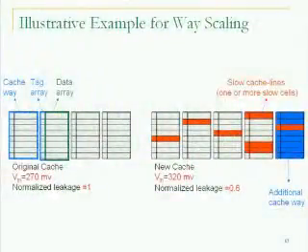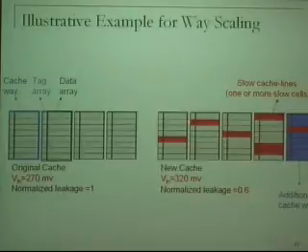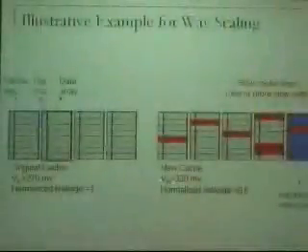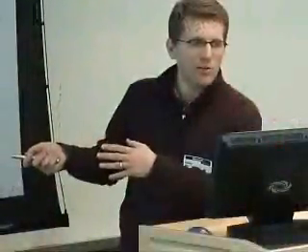We propose to have additional cache lines, additional cache ways. In other words, let me show this slide. At the beginning, you have a 4-way cache here. Then you increase VTH from, say, 270 to 320. And some of the cache lines now become delay violating. How do you take care of them? You add an additional cache way here. But since increasing VTH results in exponential reduction of leakage, the linear increase in the number of SRAM cells, in terms of the additional cache way, would still benefit the final system.